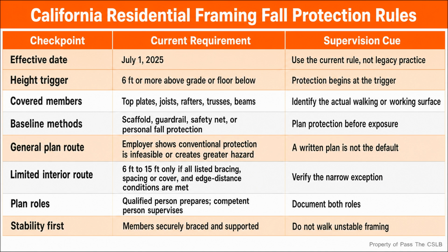Third, I separate the ties by location and force. Low means rafter tie, tension, and outward thrust. High means collar tie, wind uplift, and ridge separation. One does not casually substitute for the other. Fourth, I check intermediate support. A purlin cannot be smaller than the rafters it supports. Its braces need the proper size, spacing, angle, unbraced length, and bearing destination. I treat every brace as a load path, not as a piece of lumber filling empty attic space.